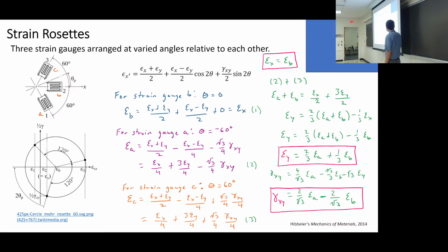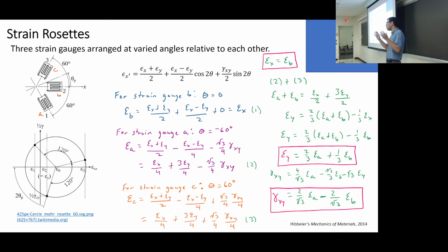And it's useful because I may not really care about the strain that much, but I probably care about whether my structure is going to fail. So I can relate these strains to the stresses through these other transformations that we've described. Epsilon x is equal to 1 over E times the quantity sigma x minus nu times the quantity sigma y plus sigma z, for example. I can use those constitutive relationships to figure out what the stress is in the system. I could also know that if I'm experiencing that much strain, then I'm probably failing my material.